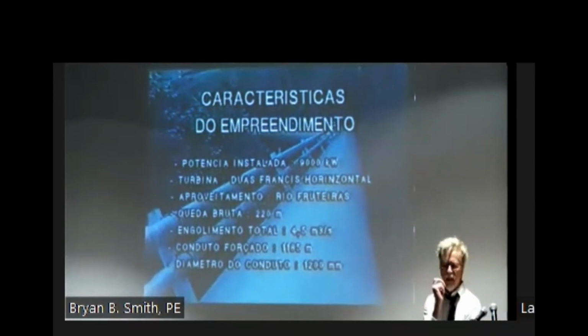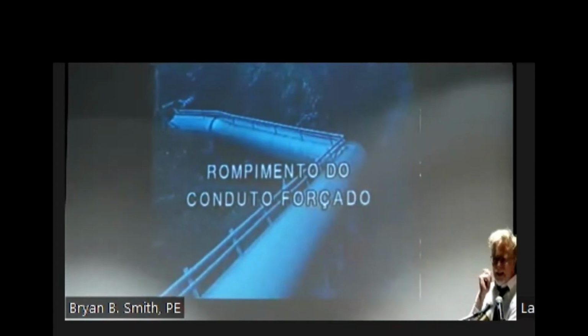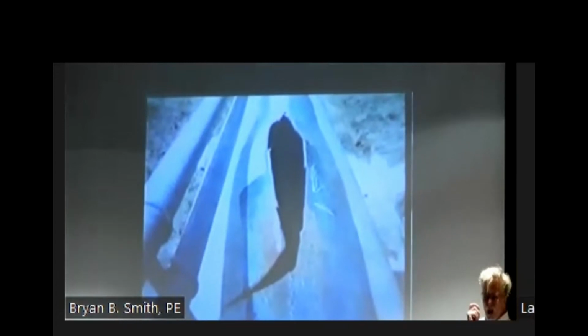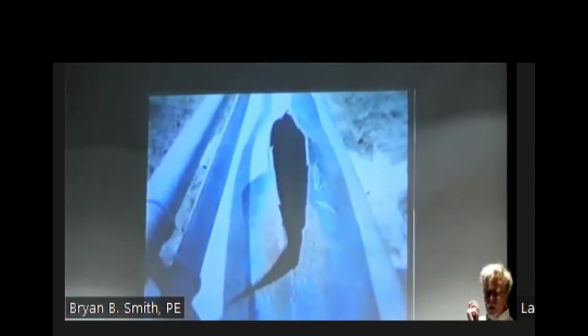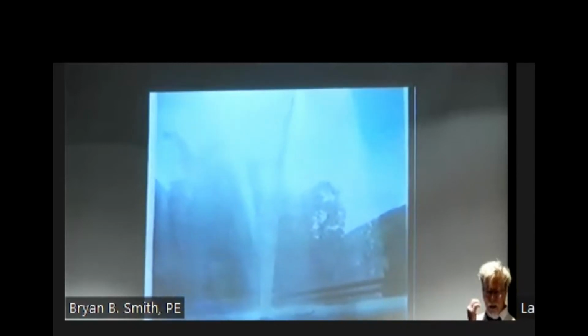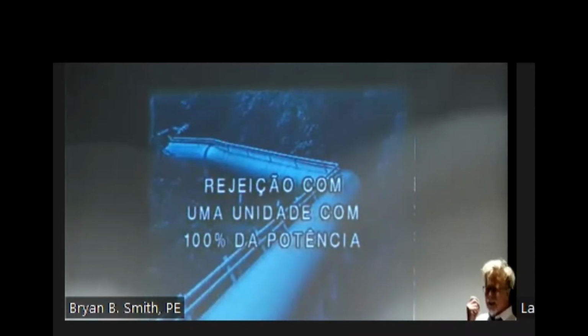So this is a large raw water piping system, and someone had the audacity to close the valve. So what you're going to see is an upsurge in pressure followed by a negative wave, just so you can see the cause and effect of a change in velocity within your system and why we need to do computer surge analysis and modeling of our system.